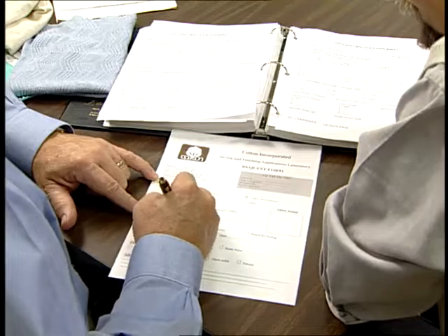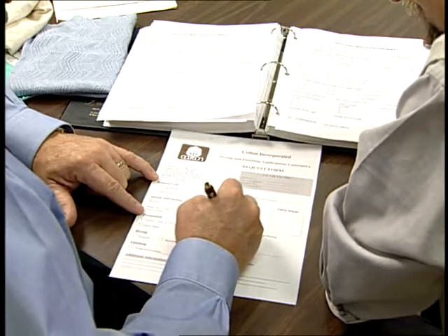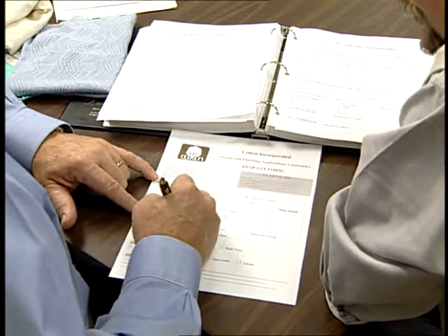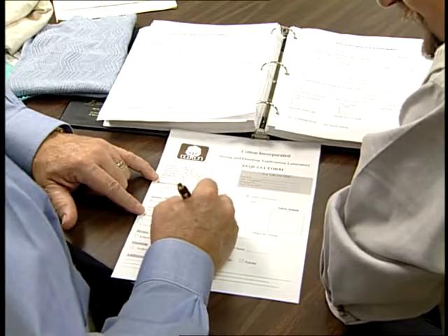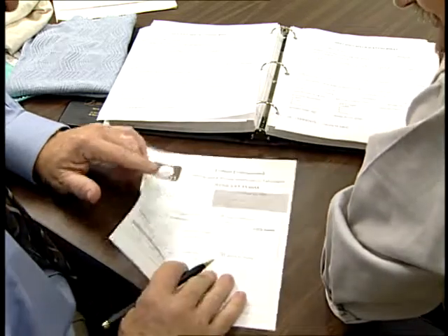Objective specifications include fabric type, weight or yield, width, strength, and shrinkage. The objective specifications may be even more specific and include machine cut, cylinder diameter, the number of needles to be used, stitch density, yarn type, yarn size, and other detailed manufacturing parameters.